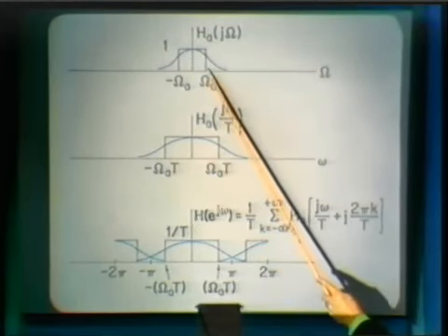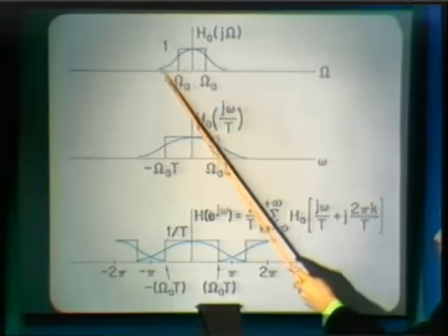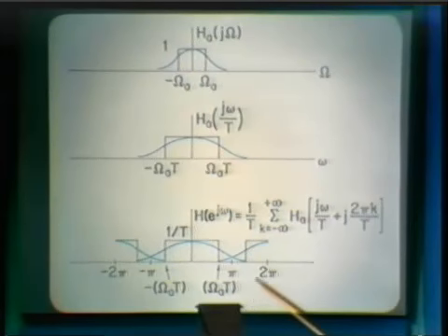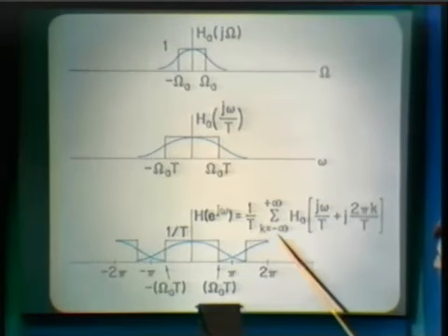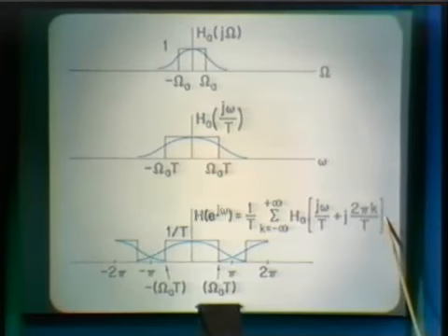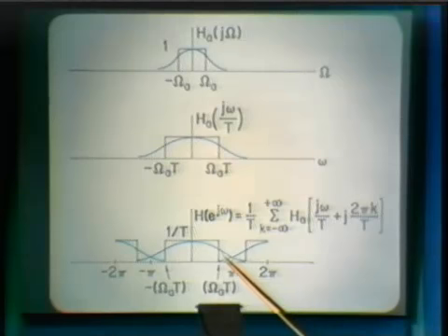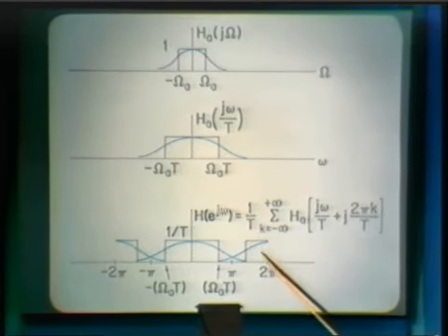So in that case, while we start with an analog frequency characteristic that's desirable, the resulting digital frequency characteristic will be distorted somewhat because of the aliasing that results due to the separate terms that are added together in this sum. And one of the important aspects of implementing an impulse invariant filter design then is to, in some way, account for and hopefully minimize the effect of this aliasing. All right, so